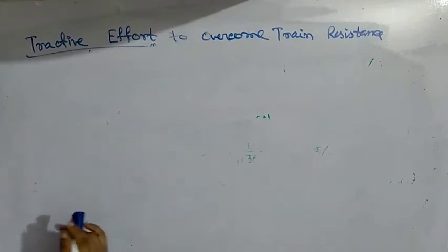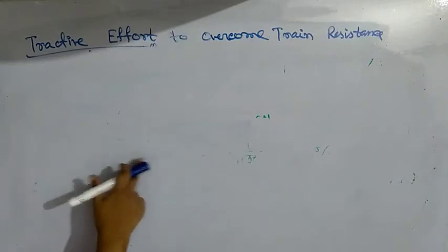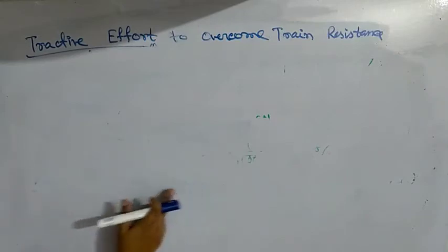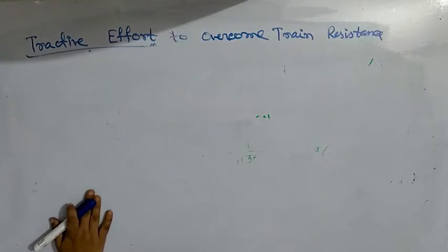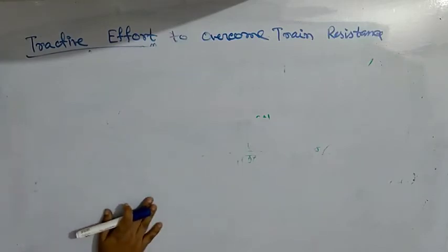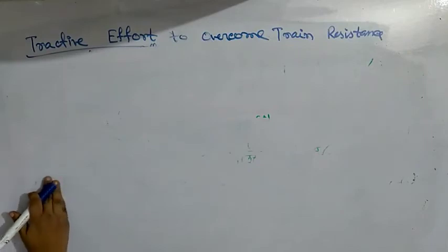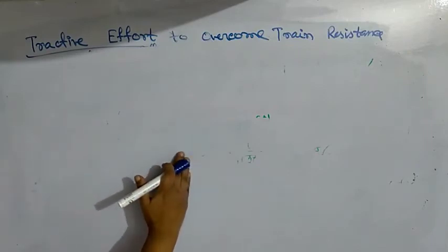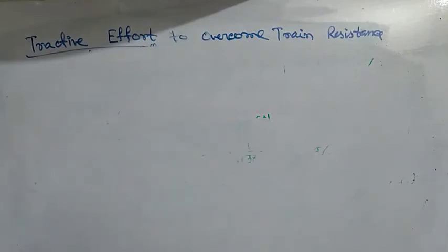End resistance comprises head resistance and tail resistance, due to suction of air at the rear, and both depend upon the area perpendicular to motion, the shape of the front and rear end, and wind velocity.